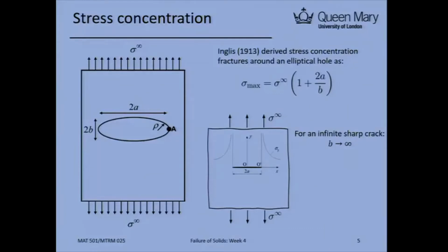In that case, you can draw the stress at that tip. The stress closing to that tip will be infinite, so you couldn't quantify that, basically. If you go along the crack tip, the stress gradually reduces in a relationship like that. So the sharper the tip you create, the higher the stress concentrated at that tip, which easily helps you break your material.